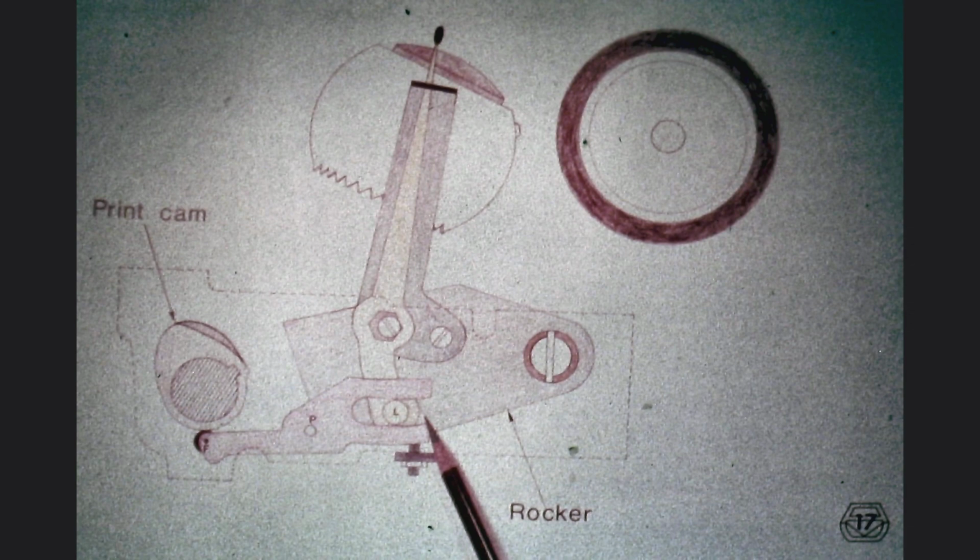When the impression control lever is set in the number 1 position, the stud L is closest to the pivot point P of the print cam follower, and the amount of motion coming from F transmitted to L is at its smallest. This means that the distance which L has to travel because of the oscillation of the cam follower is relatively small. However small it is, the distance point L travels must be covered in the amount of time determined by one of the lobes of the print cam. When the distance traveled per unit of time is small, the velocity is small.